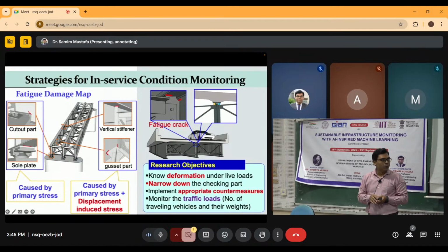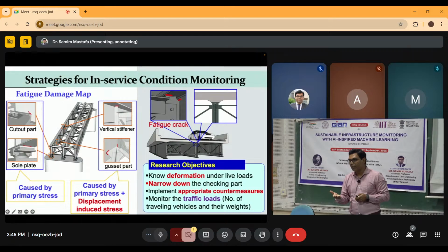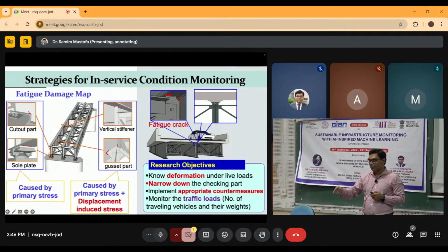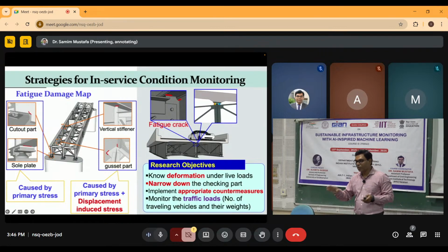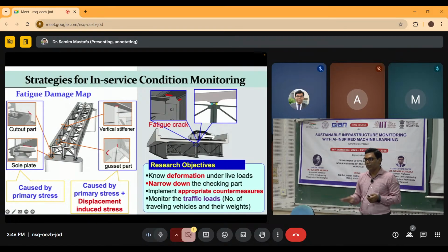So what you can do, like he has suggested, is place some sensor at the pavement, and from that sensor you can try to identify the speed of the vehicle, the number of vehicles and the weight of the vehicle. But there is a problem with that. One thing is, to install that system, you have to destroy the pavement and install the system. Then suppose you have completed installing the sensor.